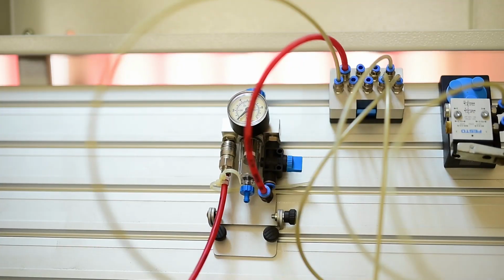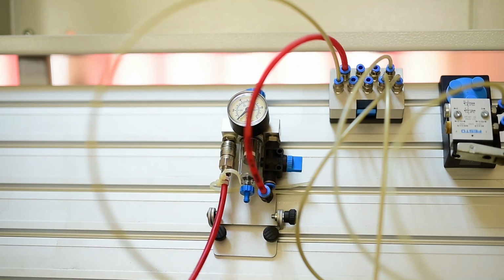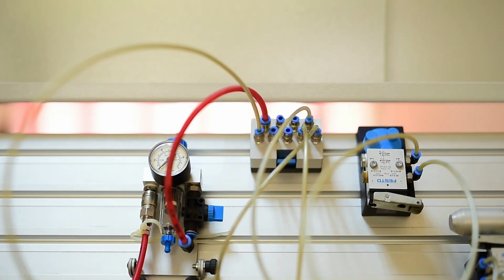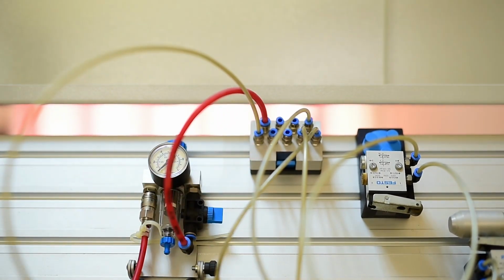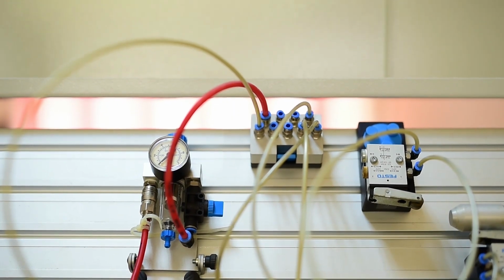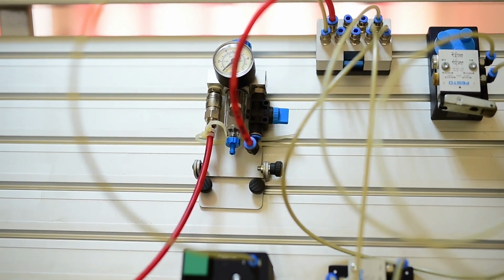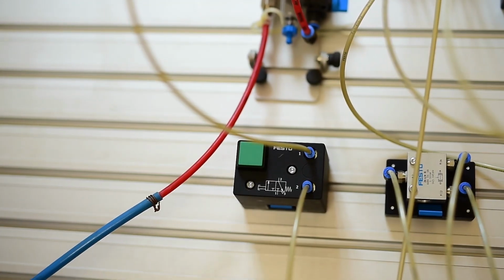Here we have a pneumatic pressure control valve which is used to control air pressure or totally cut out the air supply. After that, the main supply line goes to this multi-tube connector which provides a number of air supply points. The rest of the pneumatic circuit is connected according to the simulation that you tried. This is a 3/2 way valve with push button, which lets air supply flow through when the push button is pressed.